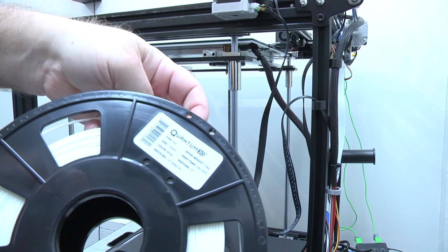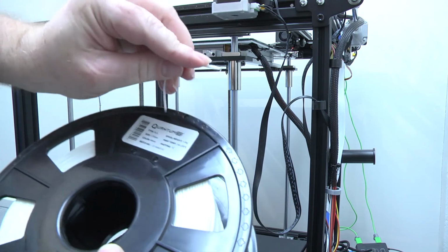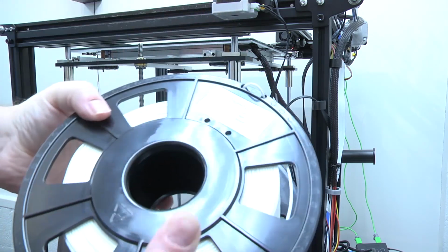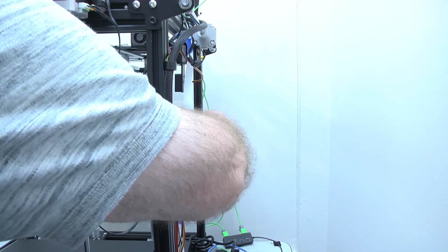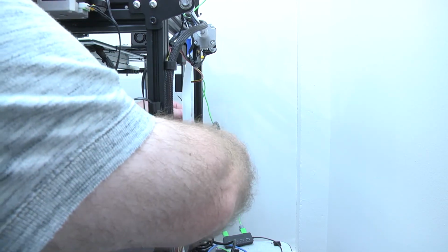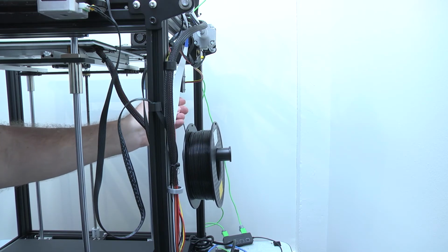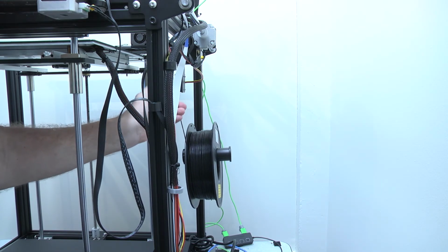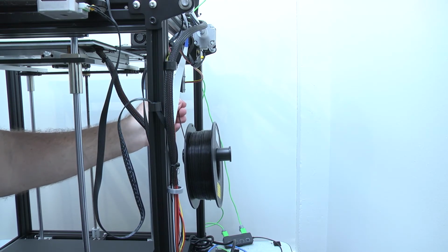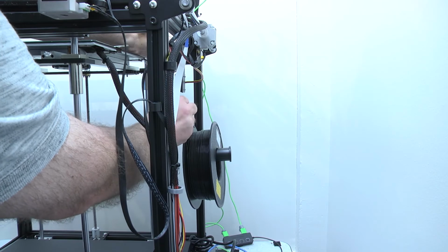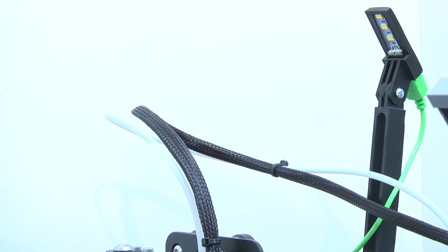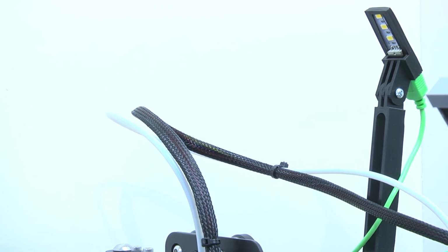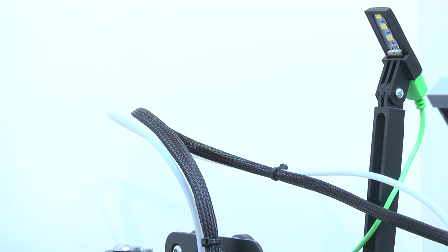When you have removed the old spool, please take the time to thread the filament through the loop to keep it from being messy. Now, put in the new color. Make sure that the filament coming off the spool is facing you and not the wall. Then, thread it into the small hole on the bottom of the filament sensor and guide it through the upper mechanism, again using the clutch to let it go through. As you slide the filament in, you should be able to see it travel through the straw to the printhead itself. Only push it until you feel it rest on the printhead. Then you are done.